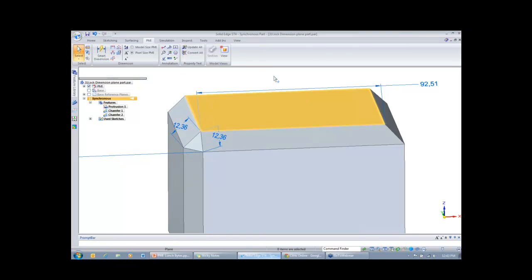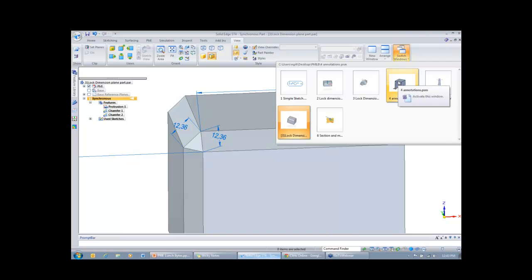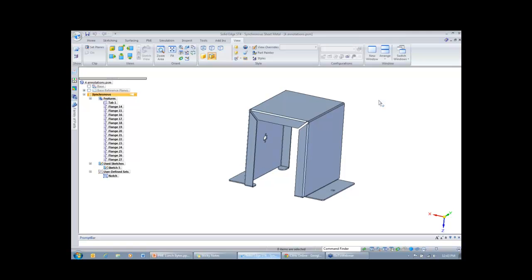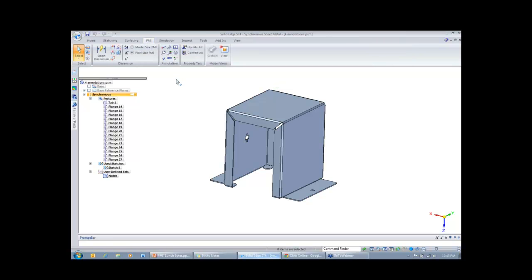All right. So next, from here on, we'll talk more about how to put PMI dimensions and also annotations, and how to bring those annotations and dimensions onto your drawing sheet. As an example, I have this sheet metal part. I'm going to use some of the annotations on this component, and for that I'll just go inside this callout command.